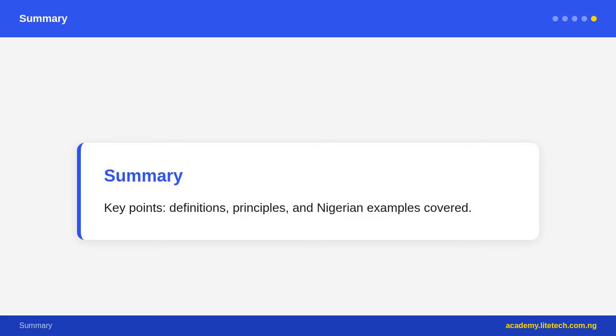Conventional spur gear drawing. Draw 3 concentric circles. 1. Outer, addendum/tip, circle, thick solid line. 2. Middle, or pitch, circle, thin chain, long short dash, line. 3. Inner, dedendum/root, circle, thin solid line. Do not draw individual teeth, unless specifically asked for tooth details.